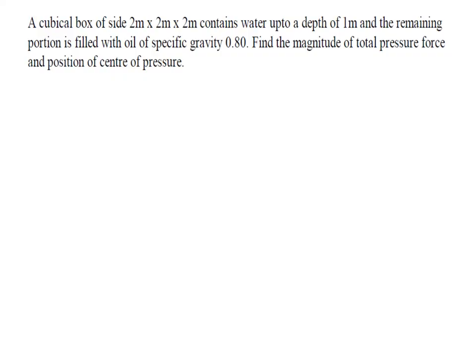If I had gone for the earlier method of finding F equal to omega A x bar and using the formula h bar equal to x bar plus Ig by A x bar, the problem would be quite difficult. However, I will show you how to calculate by that method, and then I will prove that by using pressure diagrams this problem can be solved very easily.